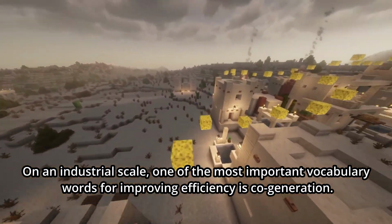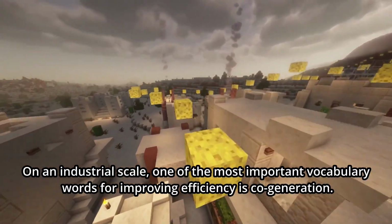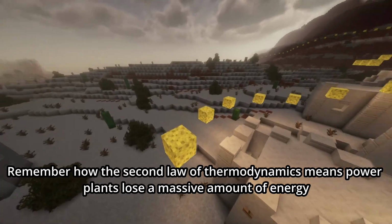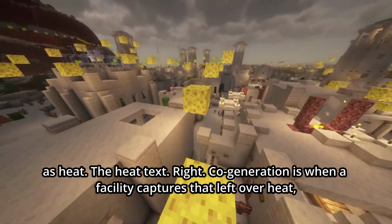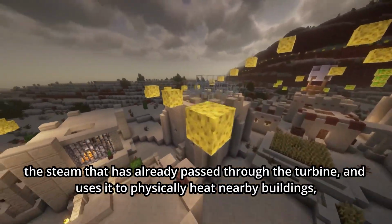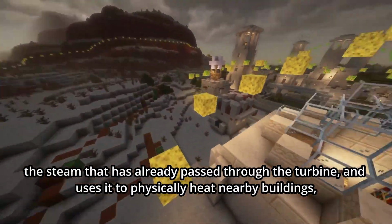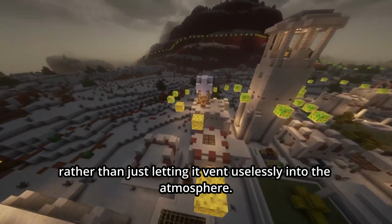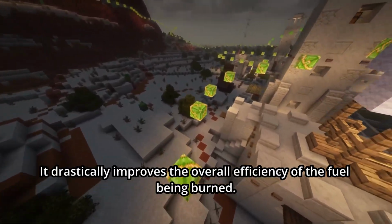On an industrial scale, one of the most important vocabulary words for improving efficiency is cogeneration. Remember how the second law of thermodynamics means power plants lose a massive amount of energy as heat? The heat tax. Right. Cogeneration is when a facility captures that leftover heat, the steam that has already passed through the turbine, and uses it to physically heat nearby buildings, rather than just letting it vent uselessly into the atmosphere. It drastically improves the overall efficiency of the fuel being burned.